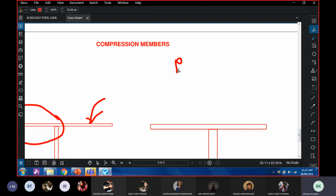So we want to find out the squash load. Force is equal to stress into area. Now which stress and which area? We are talking about yielding, so naturally the stress is the yield stress, and the area is nothing but the gross area, similar to what we had in tension members.